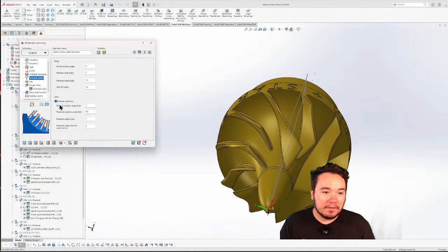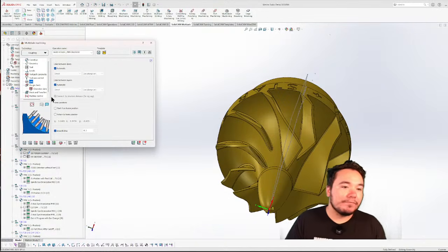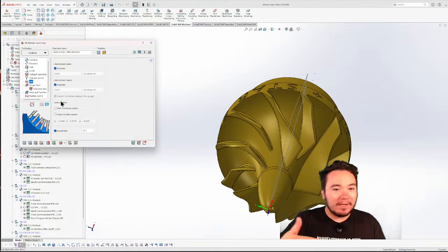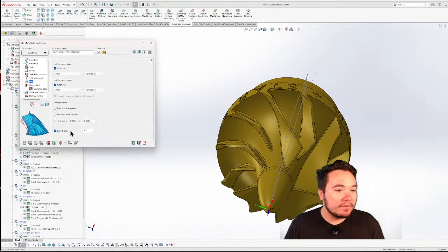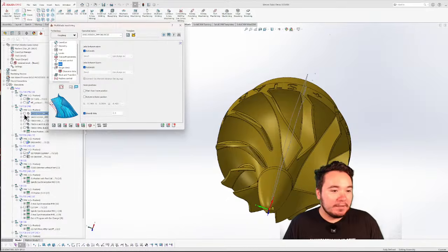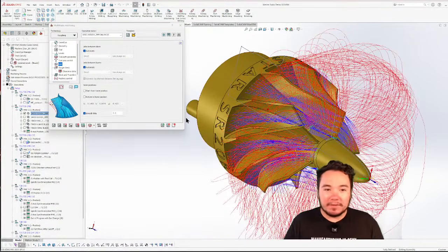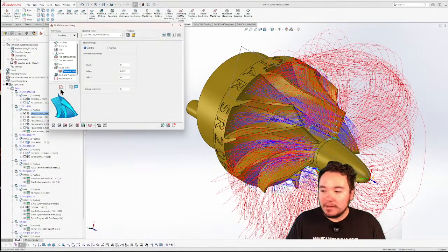We gave it a slight machining angle limit, just telling it not to go past 90, and at 90 axially, so it's stationed like at a 0 or -90, and we said I don't want it to go past, you know, 90 degrees or 0 axially. And then link, I let it go automatic. I did turn smooth link on, which is why you see that nice little curvature retract there. I thought it looked nice. It looks good on the machine. No check surfaces. It did pretty well off of that.